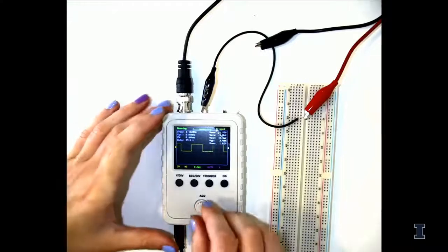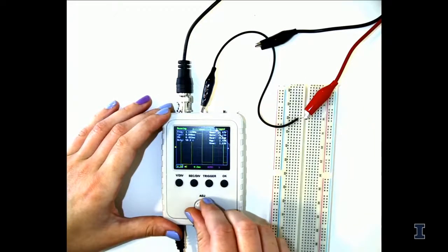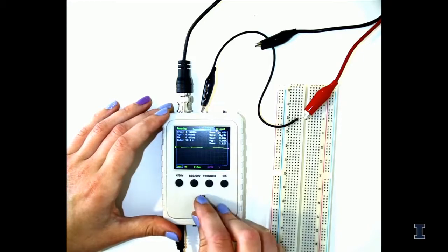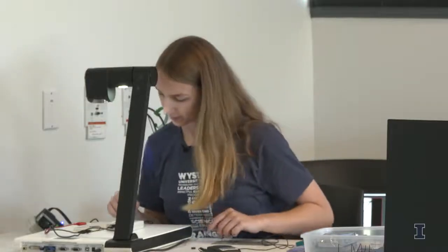Yeah. You can measure both alternating current and direct current. If you measure direct current, you should just see a line because the voltage is staying the same across time. So the range for the oscilloscope, let's just see here. It looks like you can go down to 5 millivolts as your lowest, and up to 20 volts as your highest. So you've got a pretty good range. And that's per division, right? So with 8 divisions. Oh, times 10. 4 divisions vertically, so you can measure up to 80 volts.